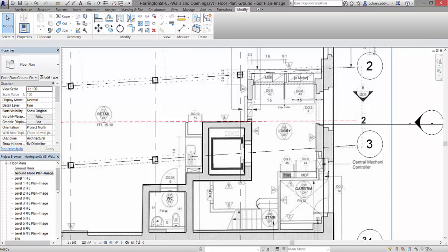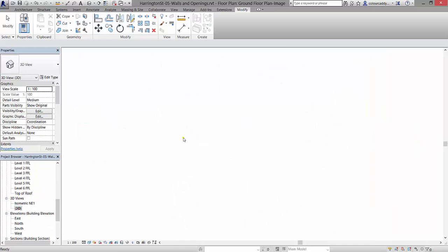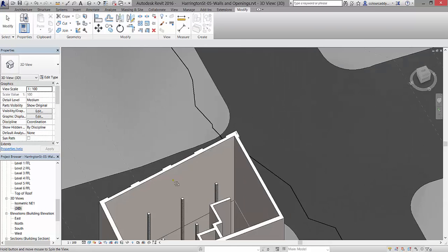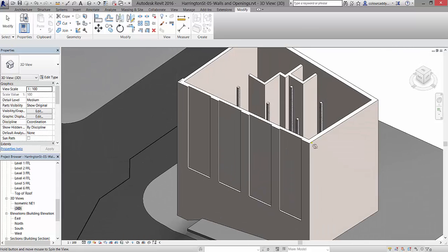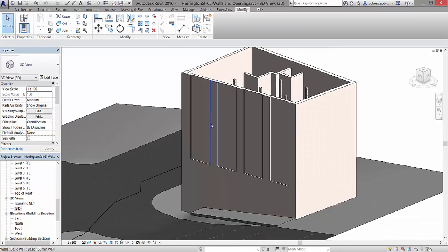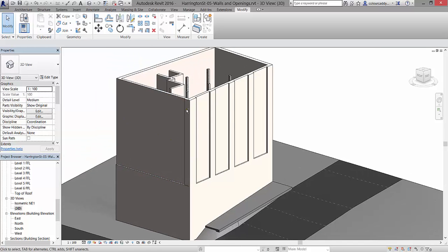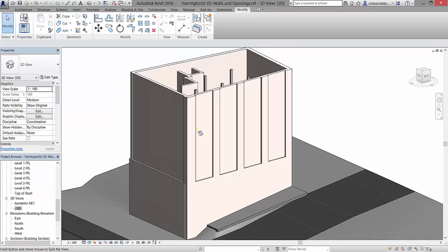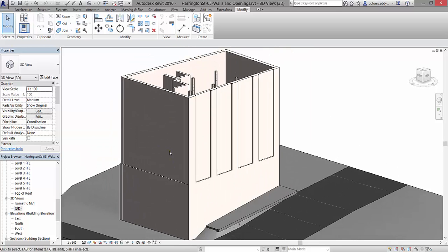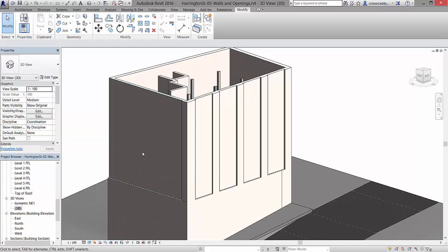Okay, so they should come through on all the levels, and if we go to the 3D view, we should see now that's extending through the building. So we've got a large part of the interior set out there as well. Okay, so you can just continue that way. So do the same setup on the facade wall over here. And then before going too far with the more detailed elements, windows and doors, and also other interior walls, I would definitely think about putting in some floors and maybe even a roof and possibly some ceilings as well. So that's what I'll look at in the next video.